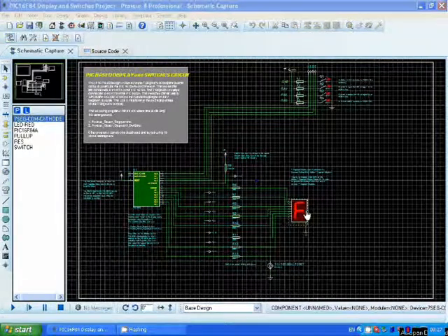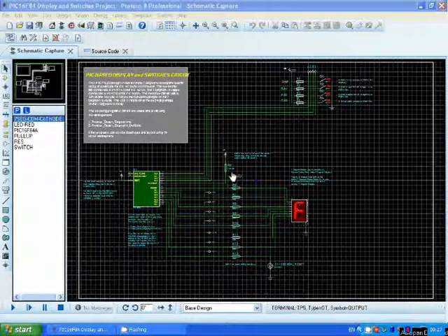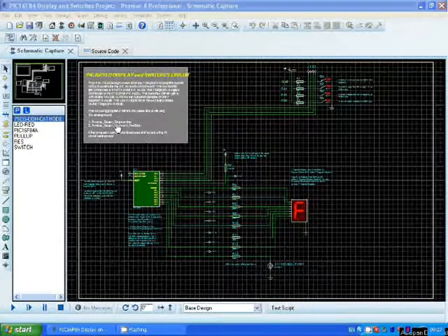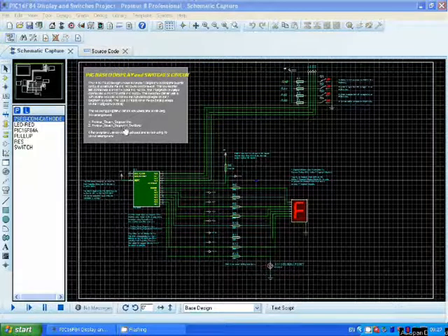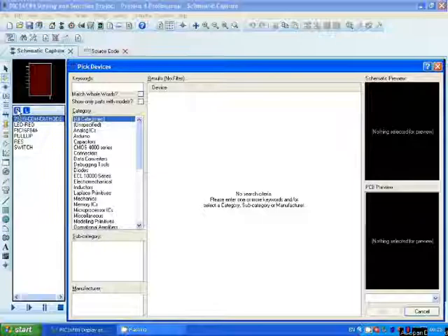And what we're going to do is, once you have your circuit built, we're going to test this particular simulation, and we have 2 test programs, Proteus 7-segment hex and Proteus 7-segment switches hex, and I'll show you both of those simulations in this video. Okay, so really what you need to do is you need to open up your previous simulation, save it under a new name, and then go over here to parts.